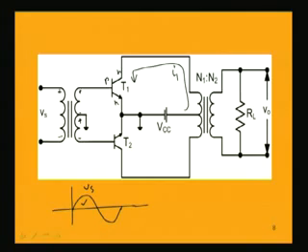But what about the other transistor T2? If we look into the other transistor T2, this is also an NPN transistor, but look at the biasing, this P is connected to negative. So, it will be reverse biased, there is no conduction taking place in the transistor T2.